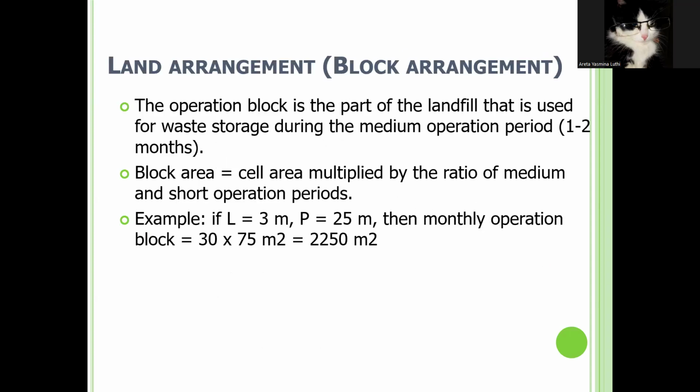And for the block arrangement, the operation of block is the part of the landfill that is used for waste storage during the medium operation period, which is 1 until 2 months. And also the block area is the cell area multiplied by the ratio of medium and short operation periods. As you can see for the example of this block arrangement, if the length is 3 meter and for the P is 20, I'm sorry, it's the width.